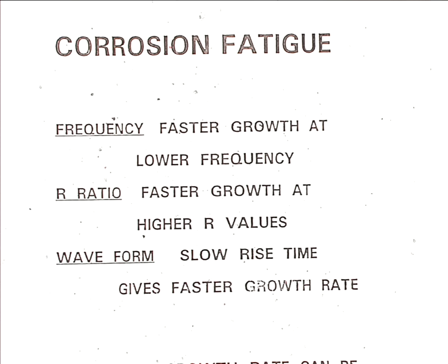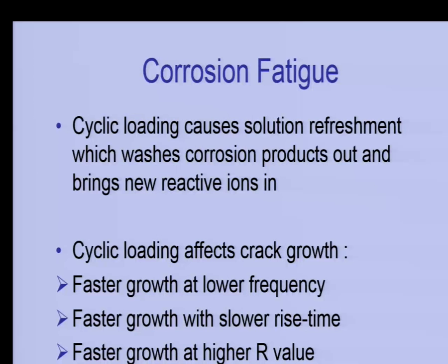So I think you've had that as well, and I think that's maybe the last slide that you had. Yeah. So that really just says in longer words what I've just discussed, which is you've got to remember that for corrosion fatigue, the solution refreshment is important, whereas in air fatigue, it's not critical. So you can do accelerated tests in air fatigue. Okay.